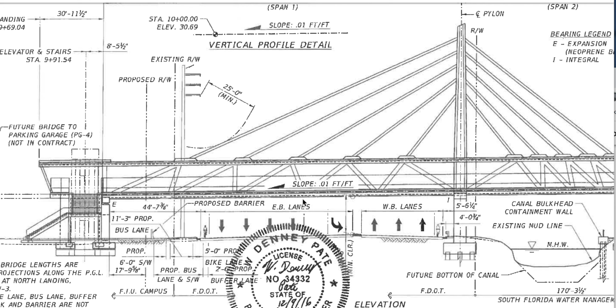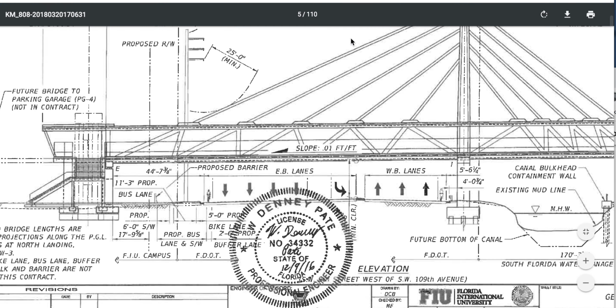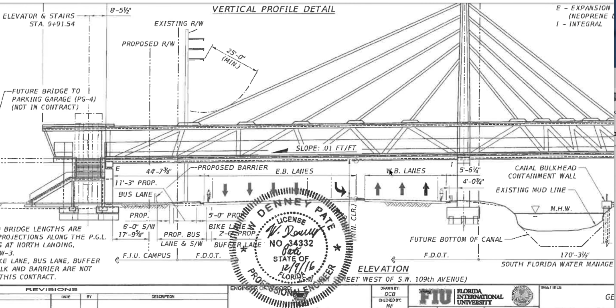They pull them tighter and tighter and tighter to the point where this deck alone can't push down. It can hold its own weight, the concrete dead load. And then they add so much more steel in there, those post-tensioning in the back end of it, as we know from other images I showed you. The post-tensioning, those black caps you guys see, makes this whole deck so flat and tight that it won't deflect. Theoretically, it will not deflect.